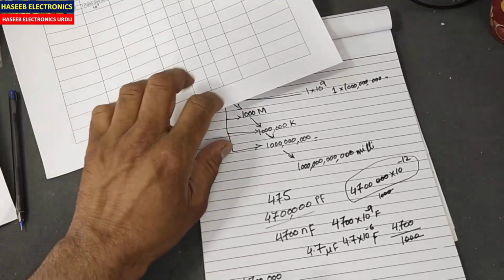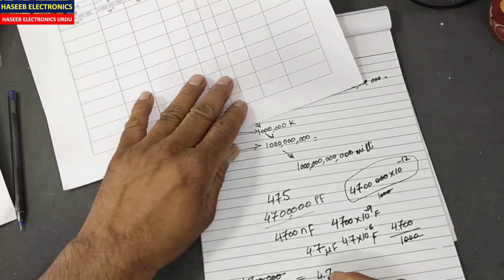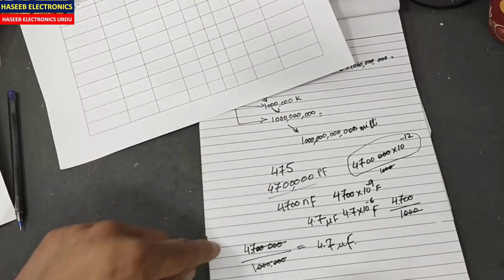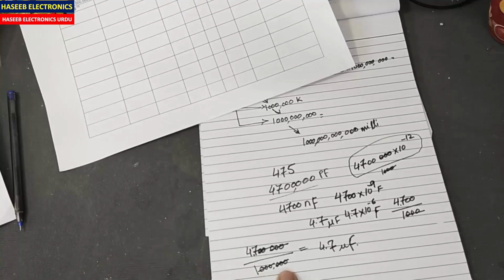So it will directly be converted into microfarad. 3 zeros here, 4.7 microfarad. We divided 4,700,000 picofarad with 1 million.